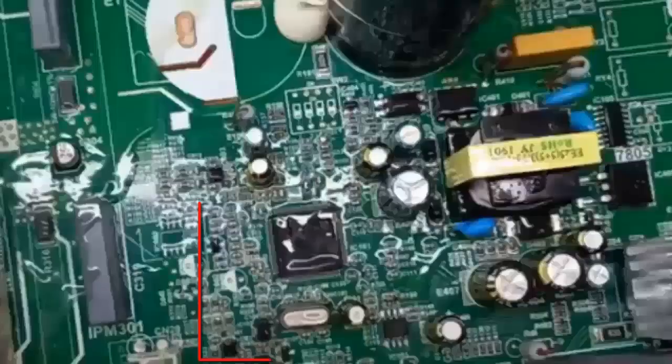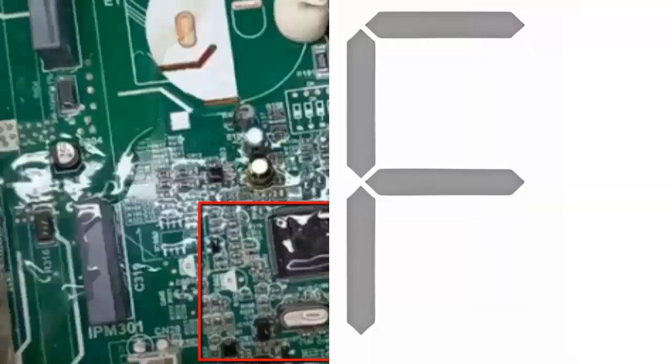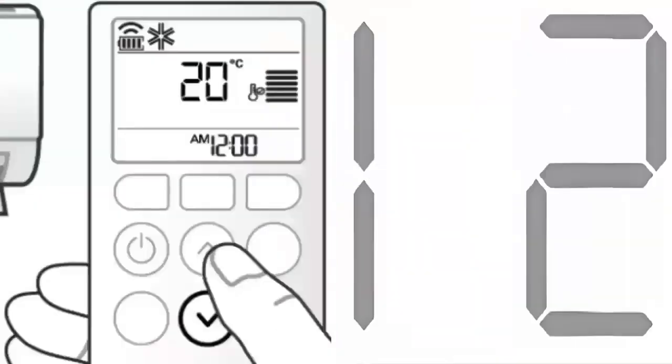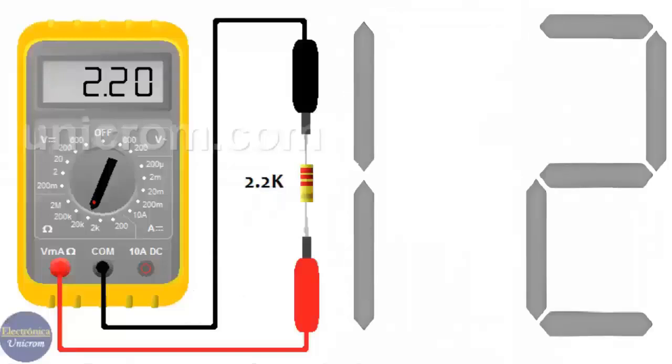4. Examine the electronic module where the F12 code is displayed. Look for any visible damage. Locate the controller on the board and the nearest integrated circuit with 8 terminals, 4 on each side.